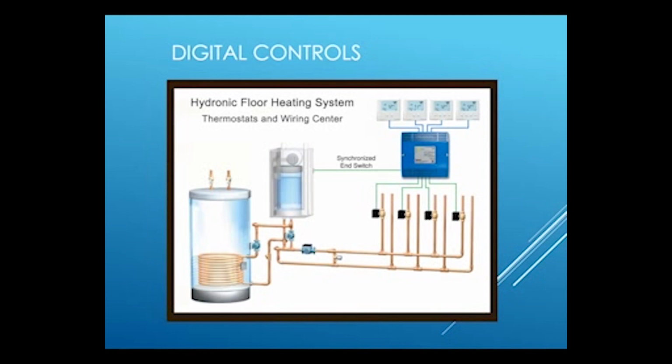All of the controls are optimized by using a digital control system. Within the digital control system, all the thermostats, the valves, the pumps, and any sensors will go back to a central unit. This will increase the energy efficiency and provide for more heating control. This utilizes variable speed injection pumps for precise temperature control, actuating motors or modulating gas valves, digital controls that monitor the outside air temperature, and that is also being used for demand prediction.